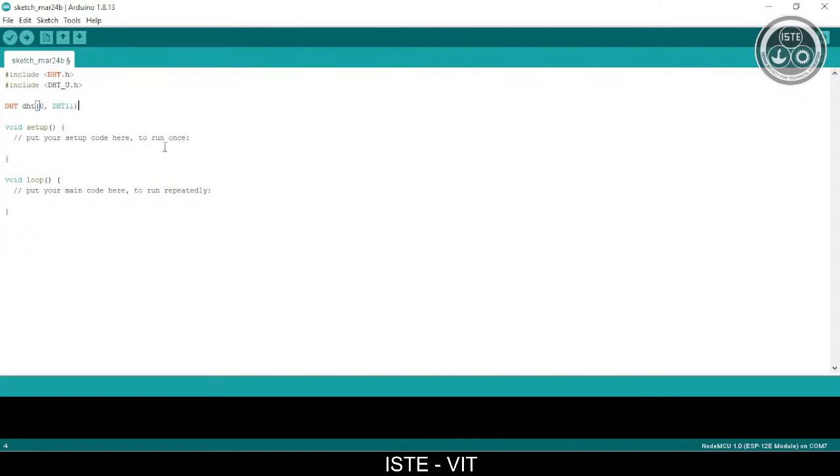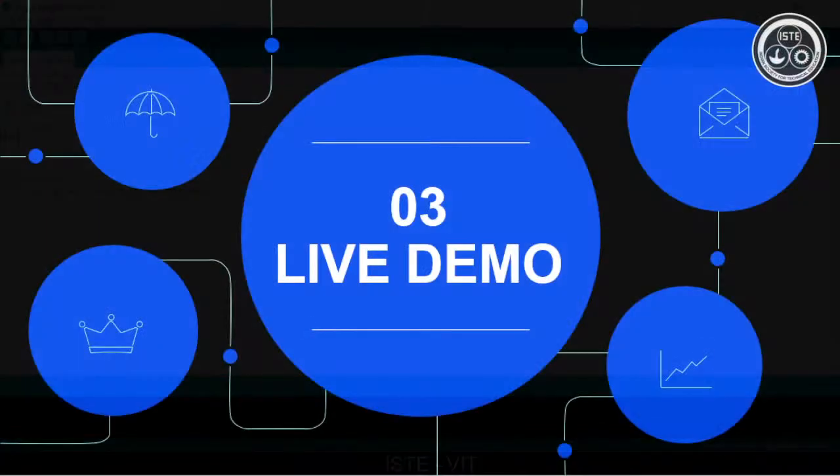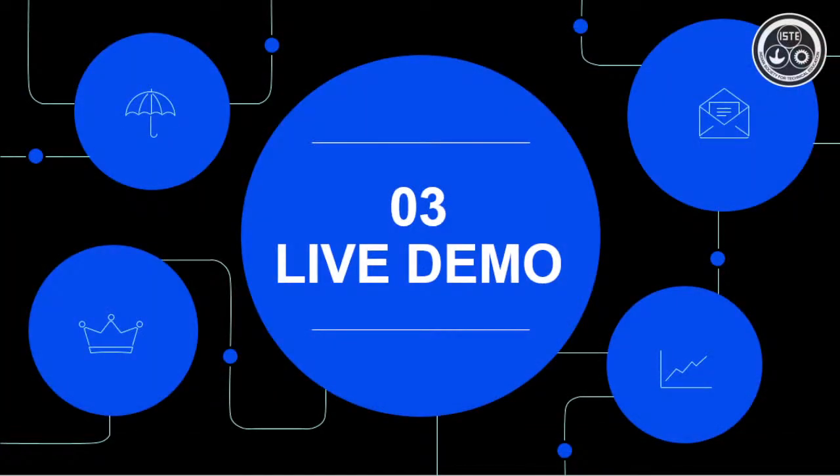In the void setup, I will be calling Serial.begin(9600). So what does this do? We want to print the temperature values in the serial monitor, right? In our screen monitor. So for that, we need to first start the serial communication between the Arduino, or the NodeMCU, and the computer. For that, we are giving Serial.begin.